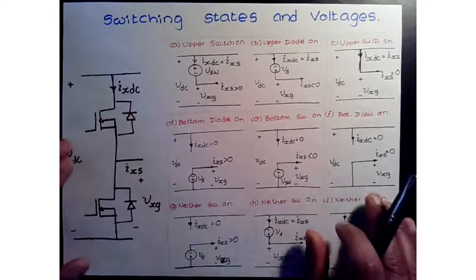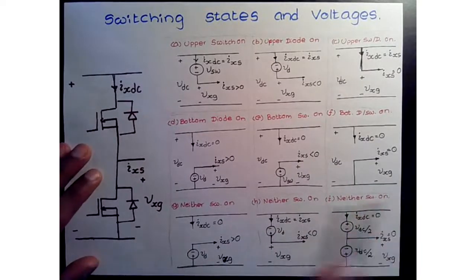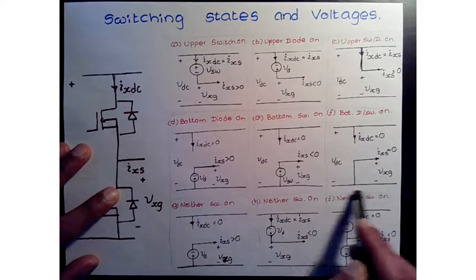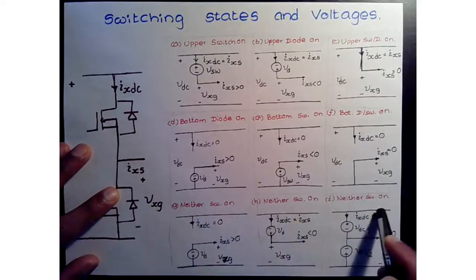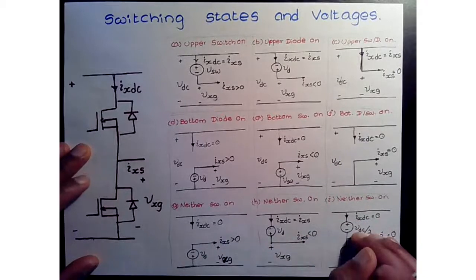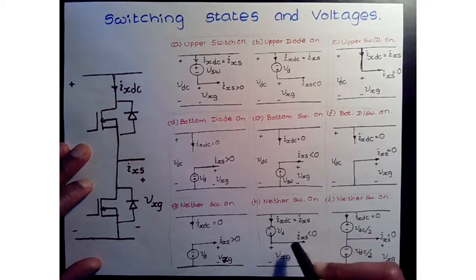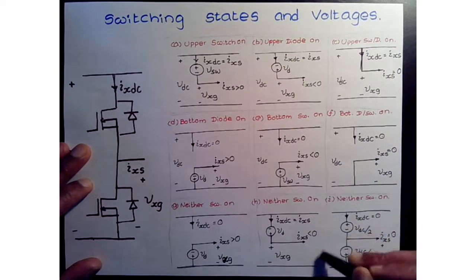Dead time. Typically, this can be programmed in your software. Okay, and then this is a kind of odd different case, but you do see them in your inverter system. So here neither switch is on. This is similar to the diode conducting. So this is the bottom diode conducting, and then here this is the top diode conducting. So current is being fed back, and this is a very rare case that you see.